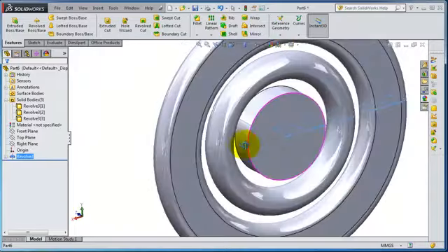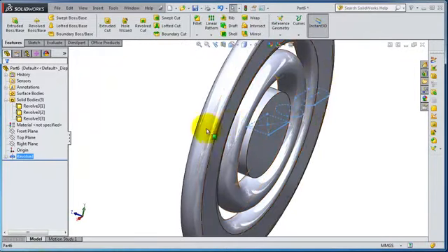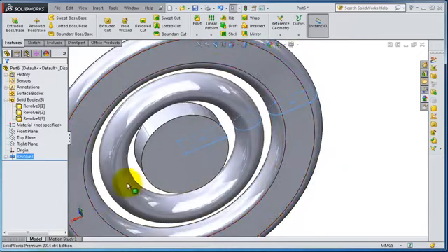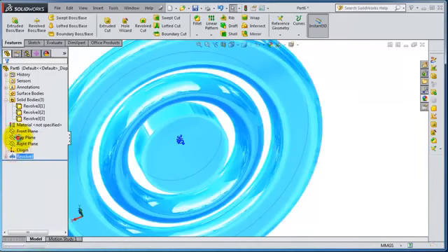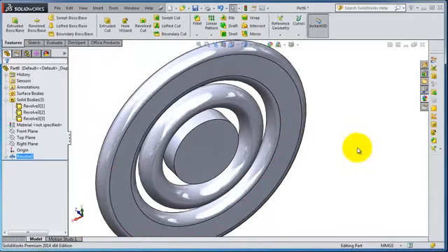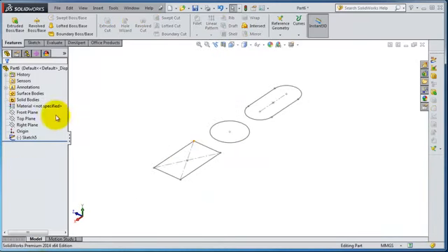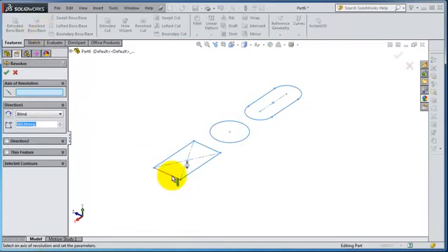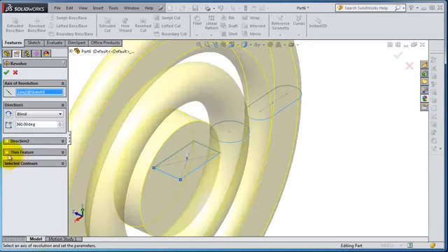So now you have this sketch. They are solid parts, and you can make things like pipes. Let's edit this and continue about revolve. Here you have the selected contours, and we don't have the thin feature activated. So let's press Ctrl C to undo. Select the sketch, revolve around that axis. You have thin feature.